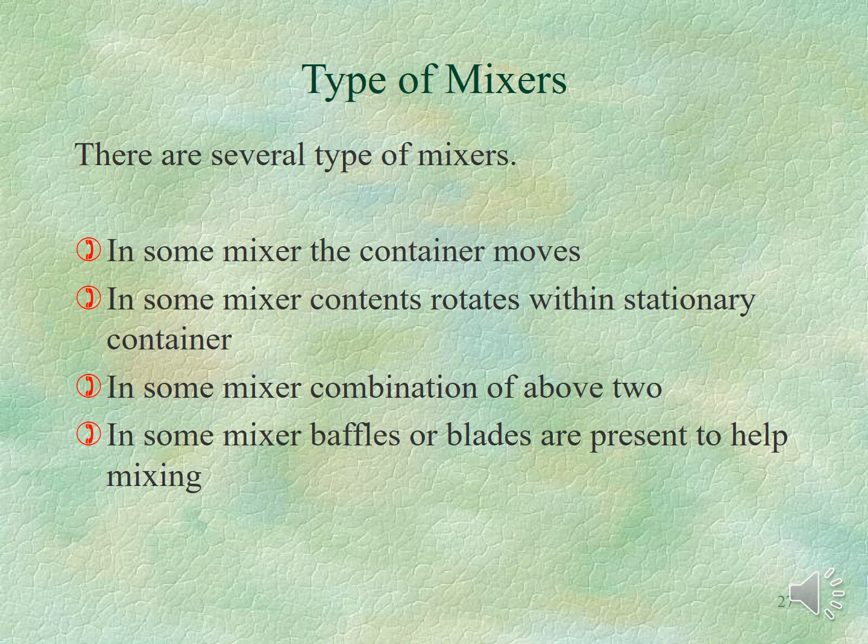So in all these processes that we are talking about, basically we are providing the powder with freedom. But initially when we discussed this topic, we said that in order to avoid segregation, we must stop providing freedom to the powder. But now we are talking about giving freedom to the powder. So we have to give freedom to the powder initially to let them move and to let them mix around. And after they reach the random mixture composition, then we should not promote freedom anymore.